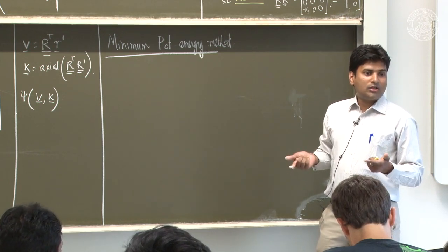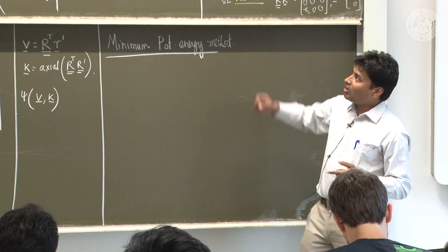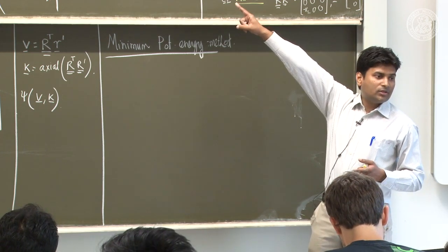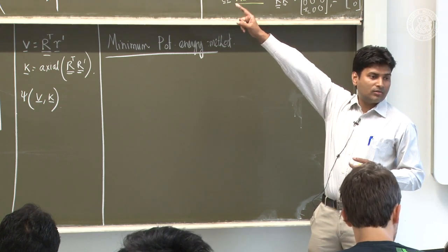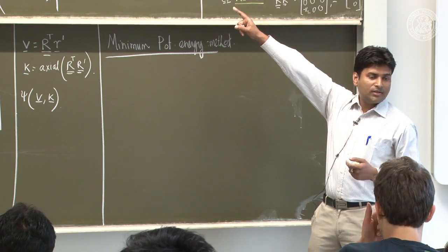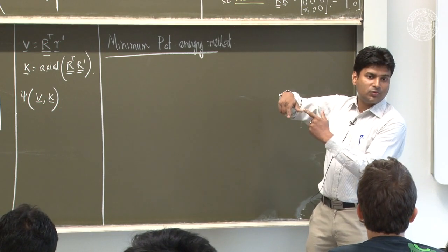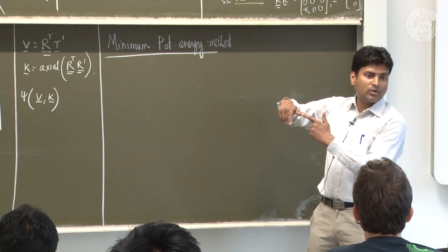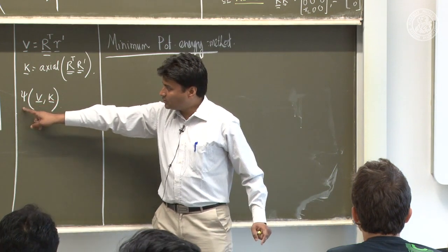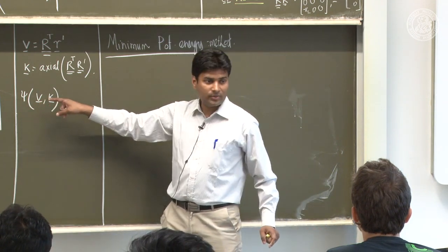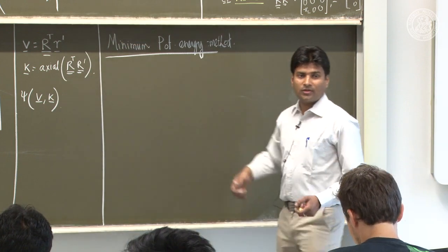And those Euler-Lagrange equations should somehow be related to the equations that we got from direct application of Newton's law. So when we compare those two, that's where we will identify that yes, the derivatives of strain energy with respect to the strain measures give us the forces and moments.